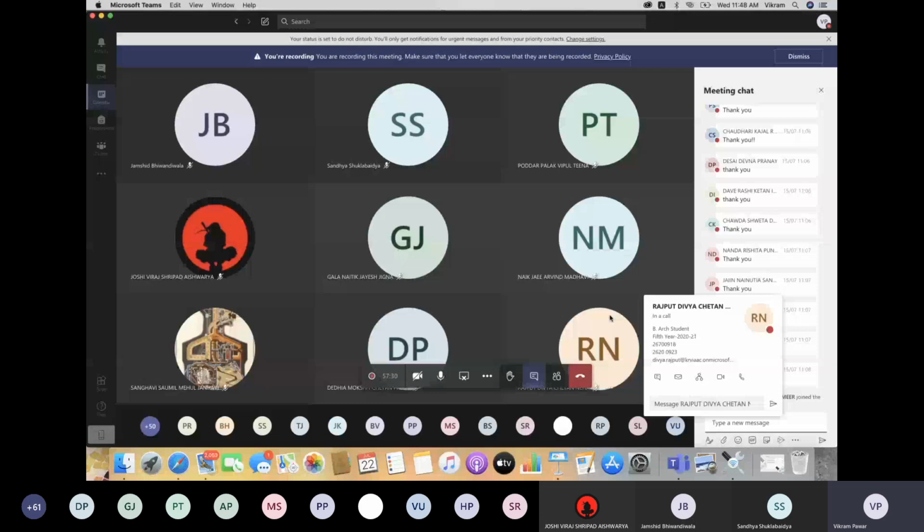For example, in these large span bridges, the supports are each minimum 50 meters apart, and the spanning members are 15 meters, 30 meters to 50 meters. If you have looked at the metro sections, how they are laid, there is a slight camber, a slight curvature towards the top. Essentially it is a component of pre-stressing.